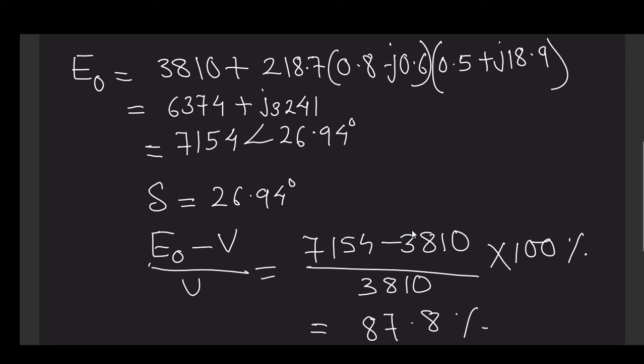That is quite a high value, undoubtedly, and obviously you would not like to go with a machine offering such a high value of regulation, because if the regulation value is this high, it indicates that your machine's performance-wise reliability is very poor, unless it is employed in a closed loop where you have some mechanism to adjust your field current according to the variation of your terminal voltage.